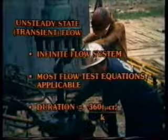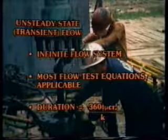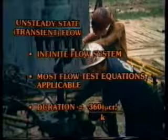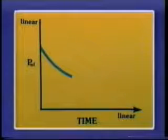The duration of this flow period is given by the relationship T equals 360 phi mu c r sub e squared over k, where T is in hours, and r sub e, the radius of the boundary, is in feet. A plot of flowing bottom hole pressure versus time during unsteady state flow might look like this.